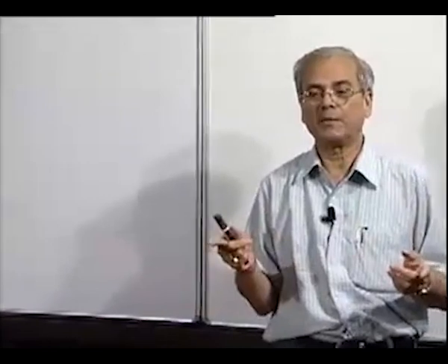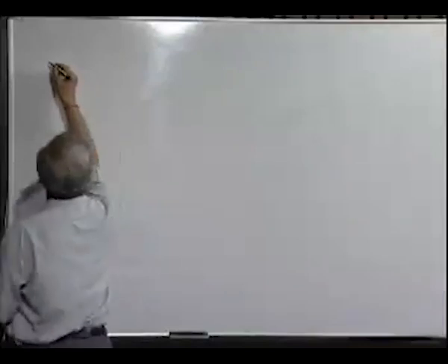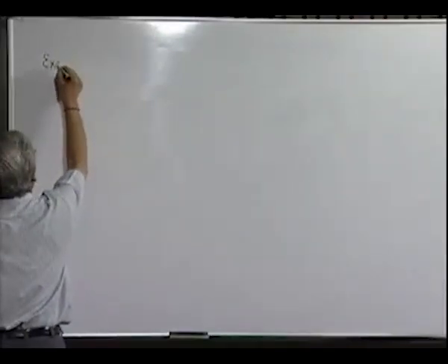Let us solve a particular example of the case as we discussed, 2 degree of freedom without any damping. What happens when damping is present? Then the various modes in the vibration of the system, the higher modes damp at a faster rate, because they execute a larger number of cycles in the same time corresponding to the lower frequency mode. So, different modes decay at different rates.